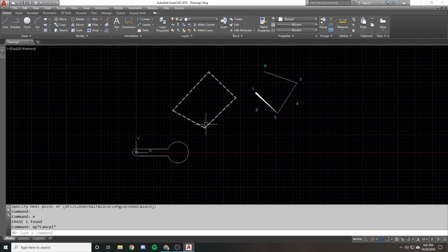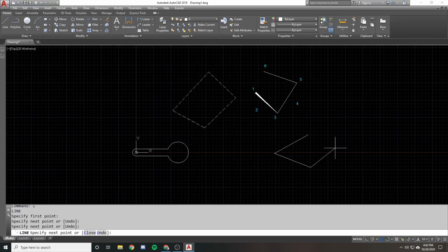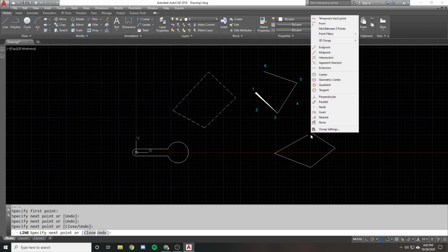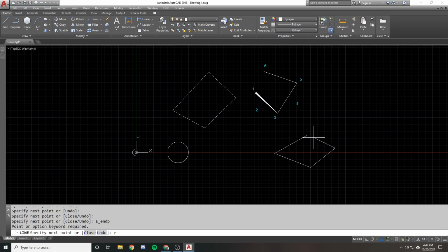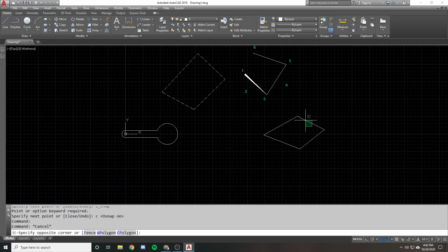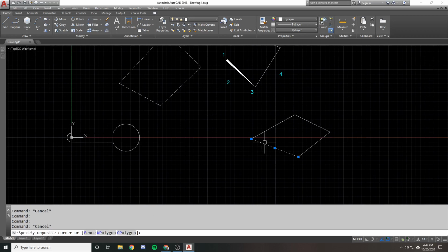Now anybody who's watching this who may already know a lot about this and is looking to glean some things may have seen me do a few lines like this, and then turn my ortho on, or osnap. Let's just close it. There. I realize I'm doing lines, not polylines. I'm getting confused. So they have individual line segments. And like I said, anybody who's watching me do this has seen me run through the p-edit command, convert it into a p-line, and then join it.